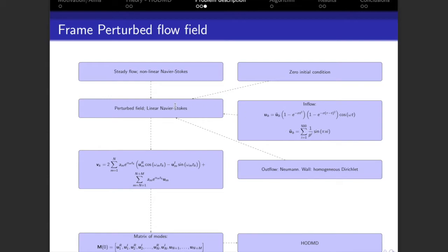In contrast to what is generally done in a classical nonlinear analysis, the outflow boundary conditions applied in the linear solver are the same as the ones applied in the calculation of the base flow. Neumann boundary conditions are used for velocity, and the remaining boundary conditions are homogeneous for all variables and boundaries.